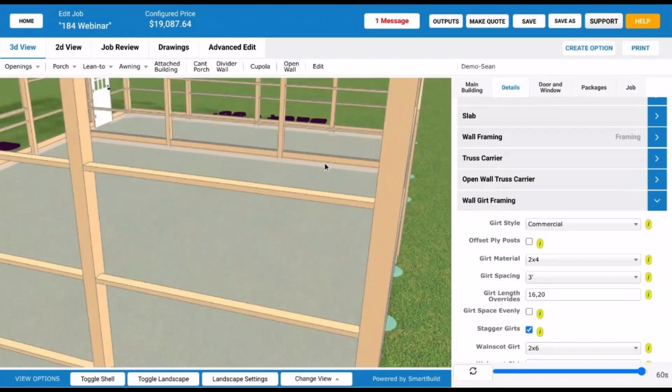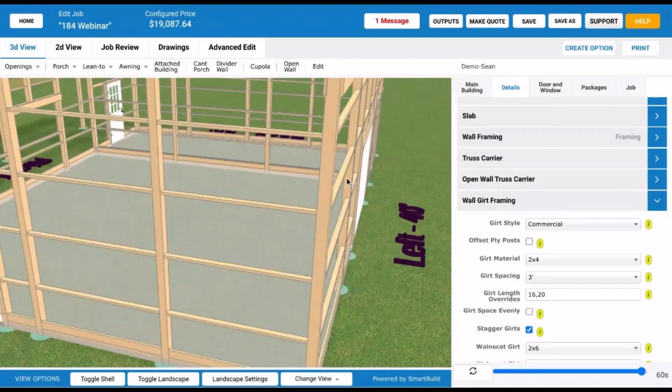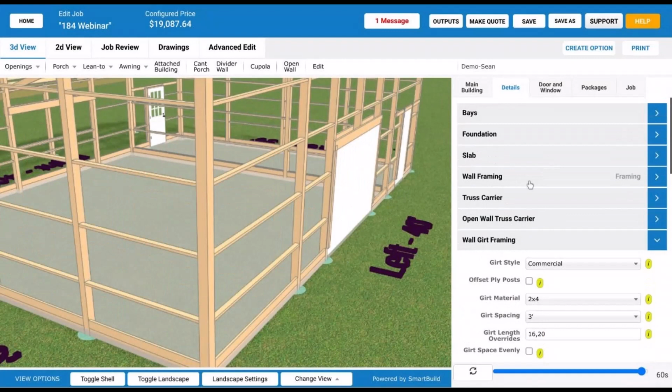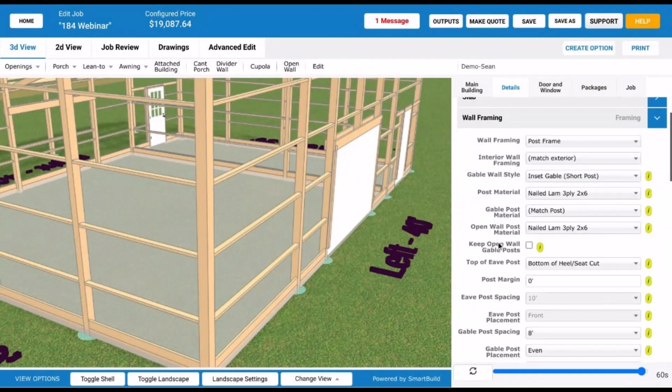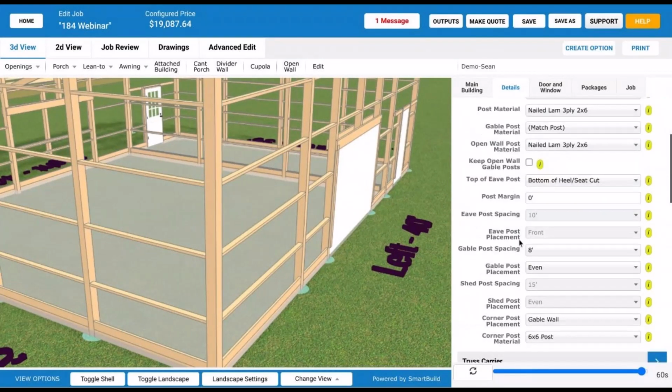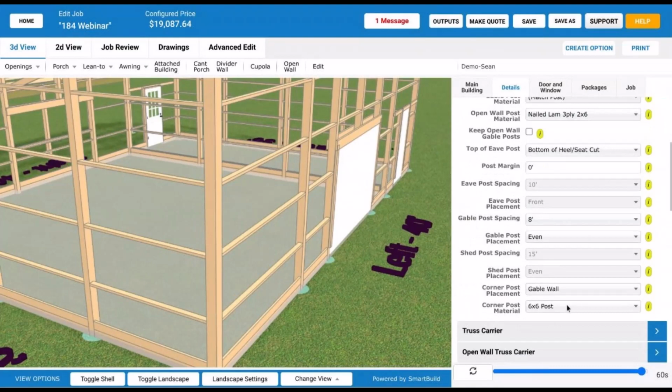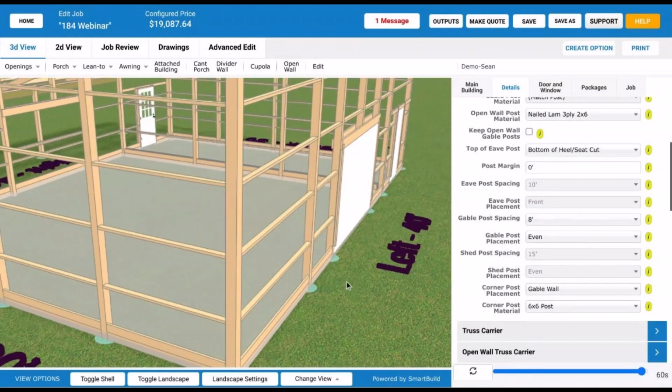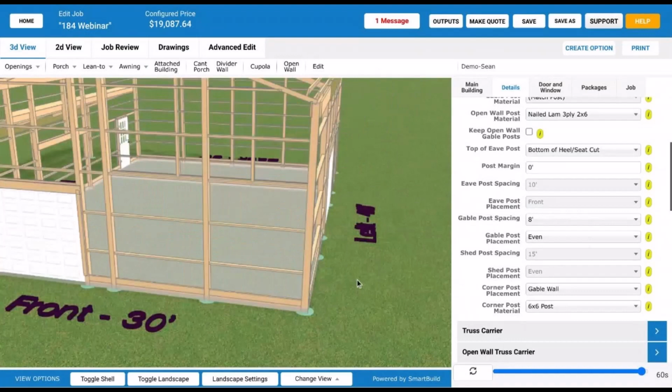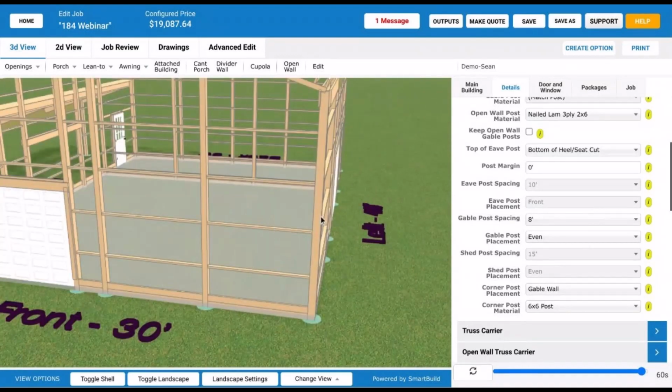But it comes to the corner. So in this case, we've got an asymmetric post. That corner post is actually in the eave wall, so the wider dimension is on the gable side of it. It's actually in the gable.